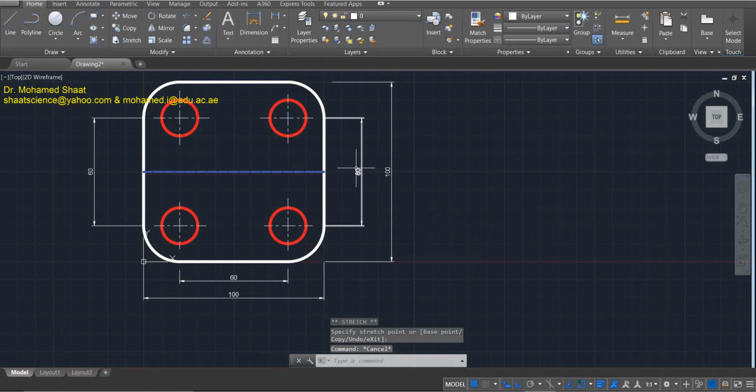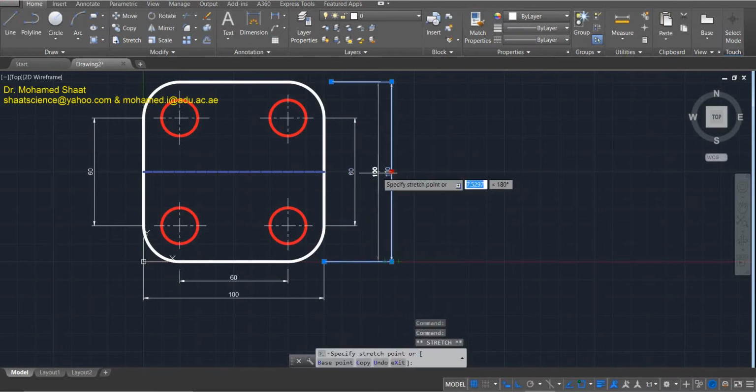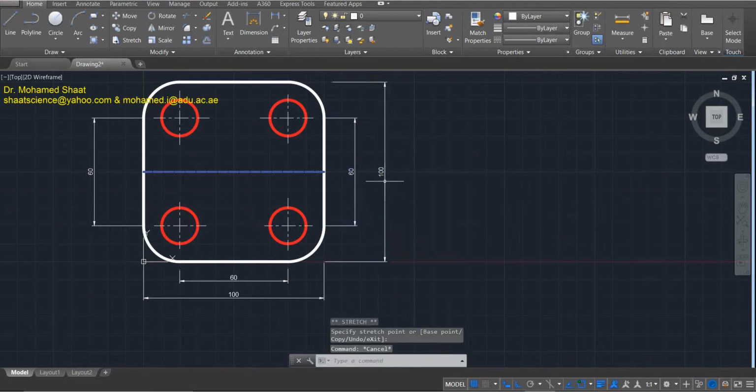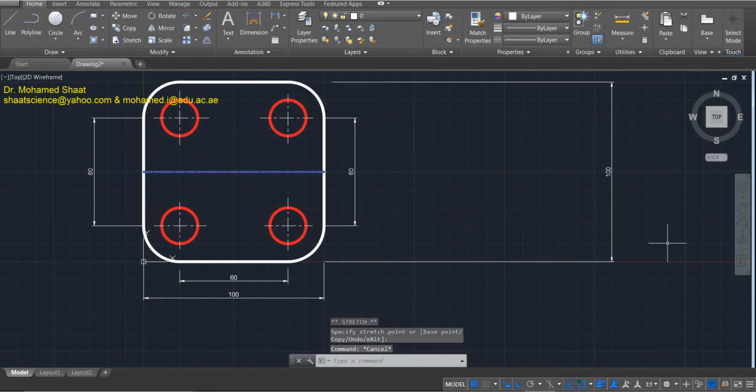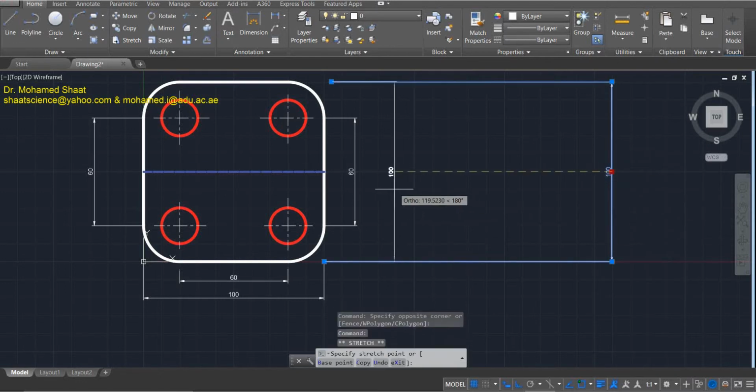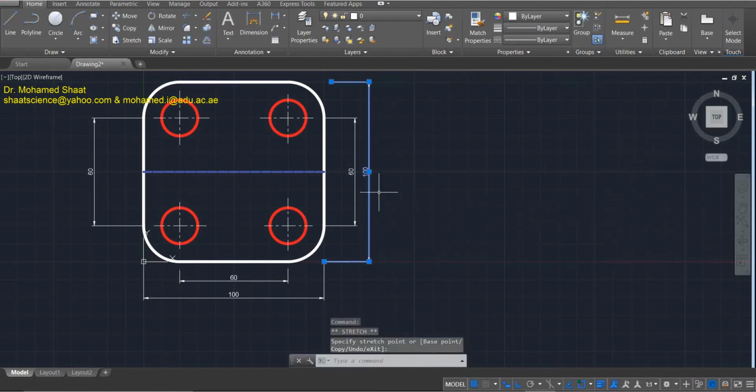Also, I can move this back a little bit. Even the space between the dimension line and the first line of the object has a standard value, right? But basically, to stick to the standard value all the time is going to be hard, but it should be consistent. So what does it mean? For example, it doesn't make sense to have this line already up there. This is not good. But it makes sense if you have the 100 here.